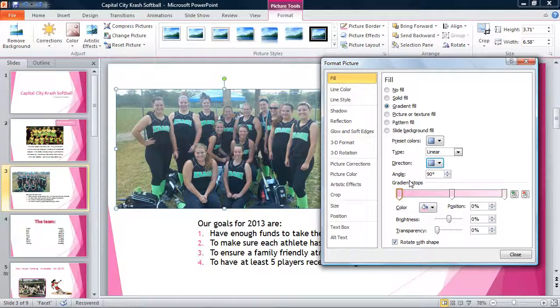The Gradient Stop section allows you to set the number and appearance of changing points in the gradient's color scheme. At its most basic level, a gradient must have at least 2 gradient stops. You can also have more if desired. In this section, click on a gradient stop to select the gradient whose properties you wish to set.